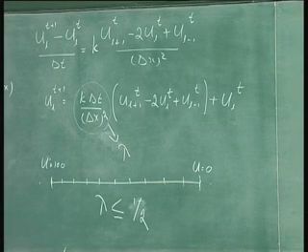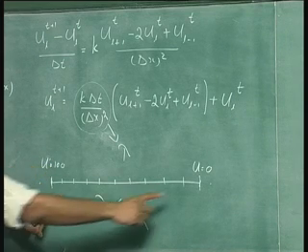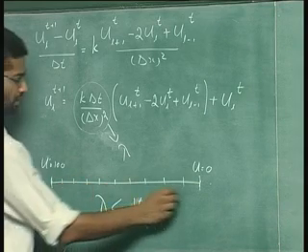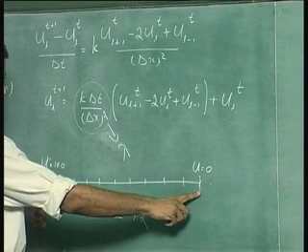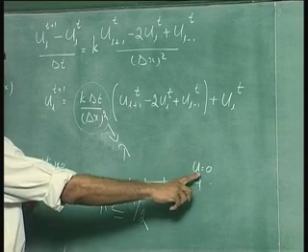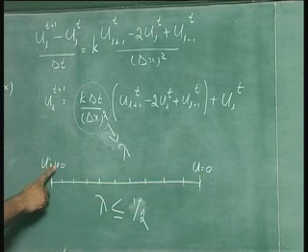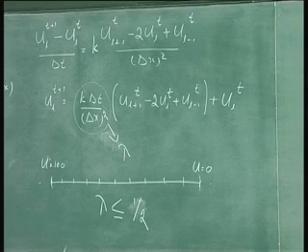So in the case where the boundary condition is specified in terms of the variable at the two boundaries, that's what the program is for. We have to solve only for the interior points. At these two boundaries, the value of u, or the temperature, is fixed for all time, as 100 and 0. And we solve for all interior points using a lambda equal to 0.5. So that's what we do.